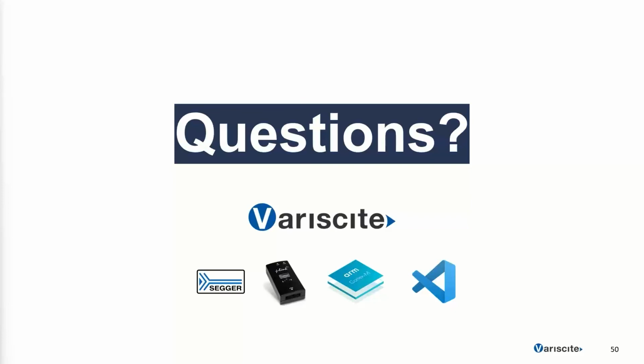There are several example projects within the FreeRTOS Variscite repository that you can look at underneath the multicores directory. The most simple one basically exposes a communication bus to the Linux side by using a serial port driver. So there's a Linux driver that manages the RP message interface between the Cortex-M7 and the A53, and then it exposes that interface to user space using a /dev/ttyRPMSG device.